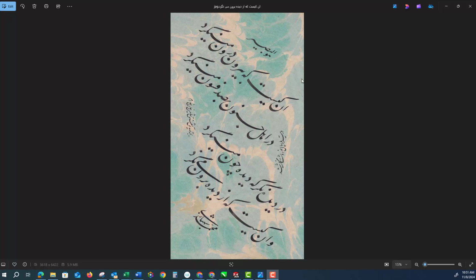So starting from here, the objective is that I am trying to choose some lines from this calligraphy. This is pixelated, and I will convert them to a vector format such that it can be imported inside SolidWorks. From there, I will be utilizing that vector as a part of a large frame, and that frame would be broken into pieces which can be easily 3D printed. So bear with me. I try to keep this one short, but still repeatable for everyone interested.